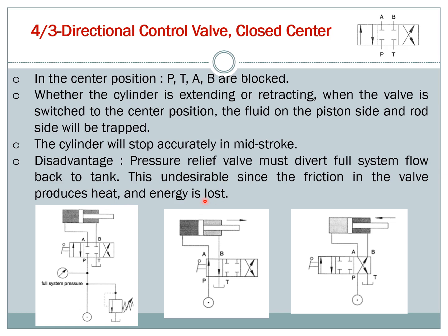On one side the damage will be to the hydraulic fluid, which will become less viscous and won't be as effective, and on the other side you will have energy loss. You need a few other steps to remove the produced heat, so you need to understand that.